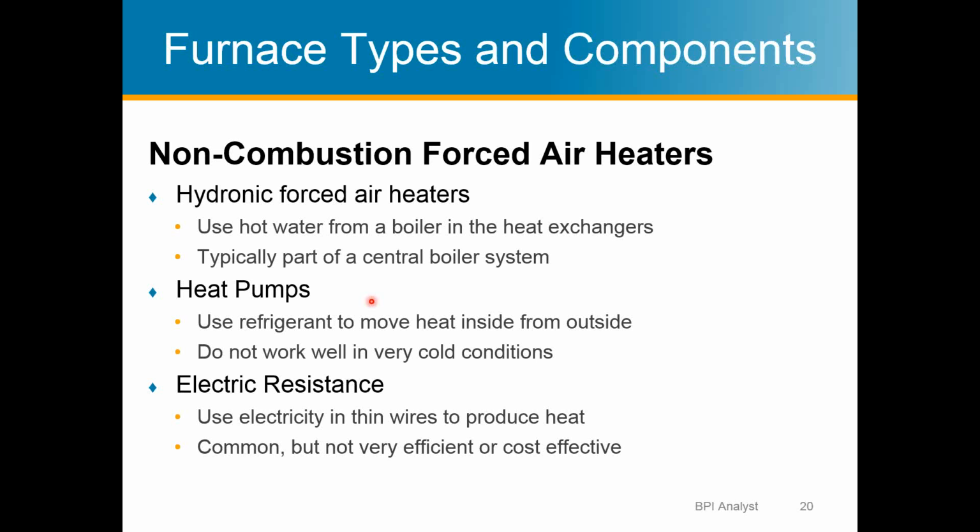So they're approaching 100% efficient, but even though they're 100% efficient, the cost of electricity is dramatically more per unit of heat than gas. So gas is used because it's cheap to operate your house. Electric resistance around 100% efficient. Heat pumps around probably 250% efficient. They're not, it's a different type of efficiency, but relatively they're really super efficient.